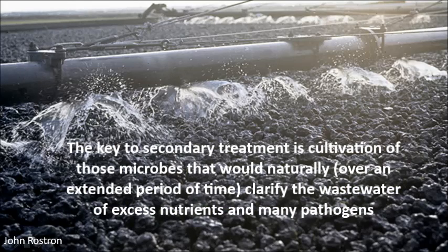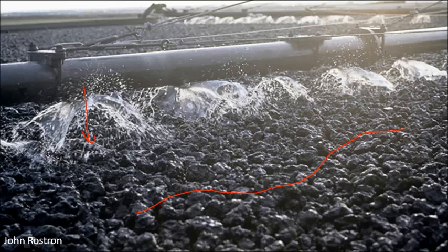So here we see, maybe we've got some activated charcoal or something here, and the primary effluent gets sprayed out onto that high surface area matrix. And each one of these carbon chunks is covered with that dense community of microbes. And the particulate matter, the organic matter that's contained within the primary effluent, serves as a food source for the biofilms that are embedded in this matrix as the water passes through it.